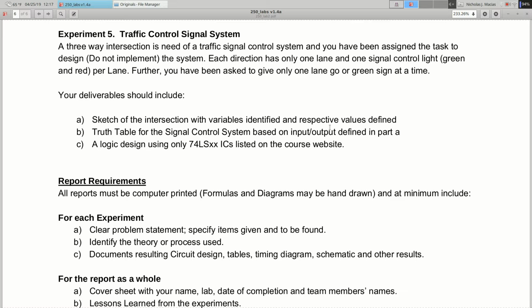So what we wanted was a diagram that included part numbers, right? And you already went through the website to find, do we have a 3-input OR gate? Well, no, but we've got some 2 inputs, and we can put those together. So you know which parts you're going to use. You specify that on the diagram, right? And then you got to specify pin numbers. So okay, well, this is coming from this chip, but which pin do I connect this wire to? Which pin do I connect that wire from?